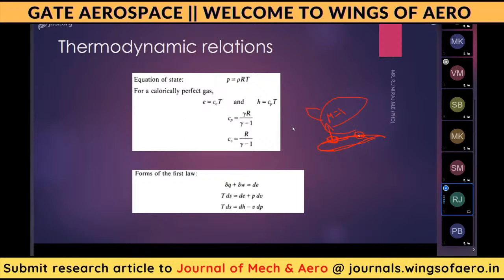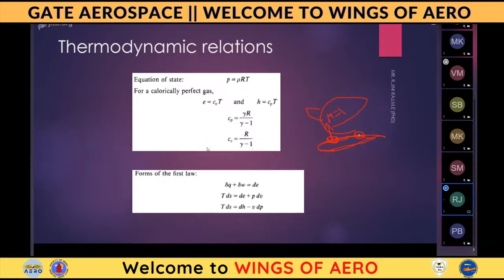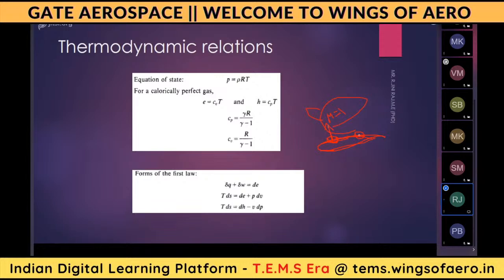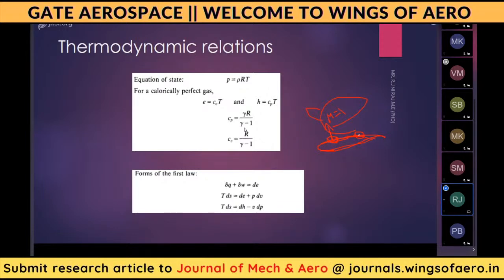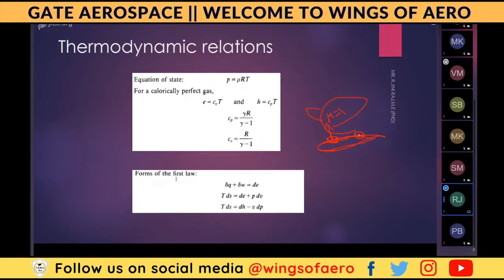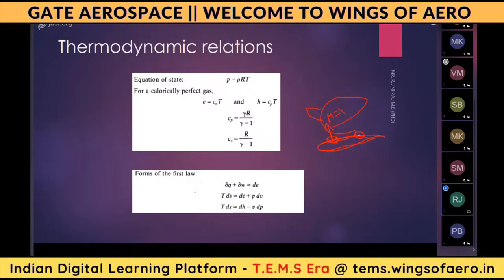At this point, it will be shifted somewhat downstream. For that purpose, the critical Mach number is shifted downstream, which means the drag will get reduced. This is the main reason for implementing supercritical aerofoils in business jets and in transport airplanes, and not in fighter airplanes. Other than fighters, the business and transport airplanes, all transonic airplanes flying at transonic speeds, are using this type of aerofoil only, supercritical aerofoils.